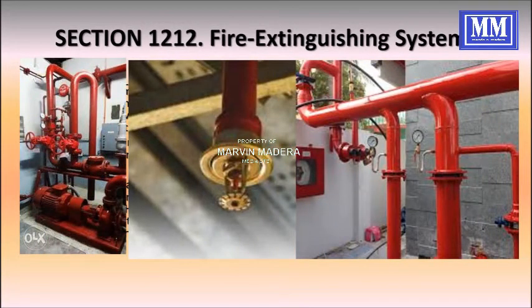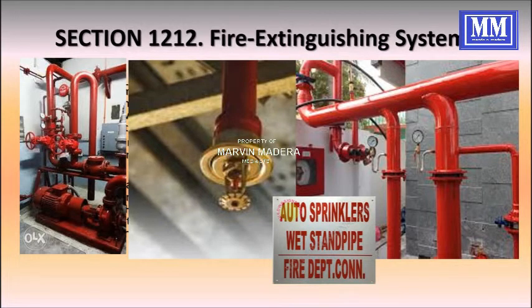We have here a sample of a wet standpipe. This is quite the same as the dry standpipe. The only difference for this one is that inside it there is pressurized water flowing inside these pipes. Once this pipe is opened, a flow of water is to be expected at high pressure. Most of these pipes also have a symbol or a signboard telling us that you have auto sprinklers, wet standpipe, or fire department connection.